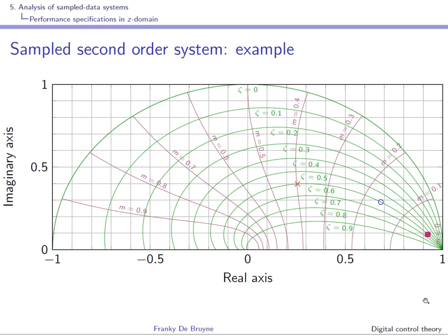So here you can observe this visually. This is the sample pole location where ts is decreasing. Okay, this corresponds to a ts of 0.25, so an m of approximately 0.4. So that's, you can see over here, and indeed you're on the curve that corresponds to zeta is equal to 0.6.